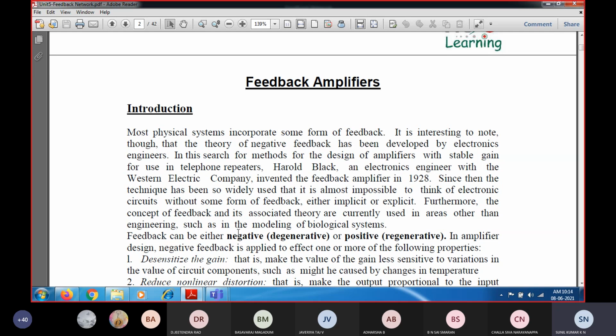So, crystal oscillators: how does it vary with respect to its crystal reactance? It has two resonance frequencies, because the crystal works with respect to the piezoelectric effect. We have seen the piezoelectric effect, and based upon the external mechanical input, it provides an alternating current, or alternating sinusoidal variations, so oscillations across the output. So based upon that, the crystal provides a sustained oscillation.